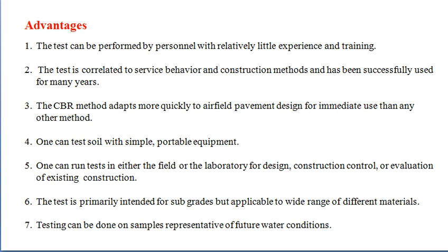The CBR method adapts more quickly to the airfield pavement design for immediate use than any other method. So it can be readily implemented on any sort of pavement, and one can test the soil with simple portable equipment. So in situ testing and laboratory testing are easy to perform. Hence this test has been preferred, and one can run tests in either the field or in the laboratory for the design, construction control, or evaluation of the existing construction.